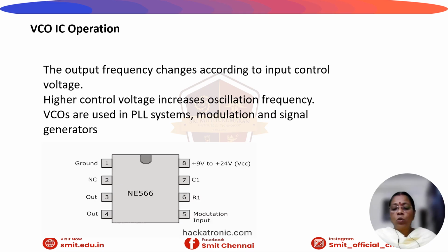They generally come in two types: relaxation oscillator and harmonic mode. The relaxation type generates square wave or triangular wave. In harmonic mode, it will be for sinusoidal RF signals. The main general IC used is NE566, which is a popular general purpose 8-pin IC capable of generating both triangular and square waves. It is highly utilized in function generators and signal generation.